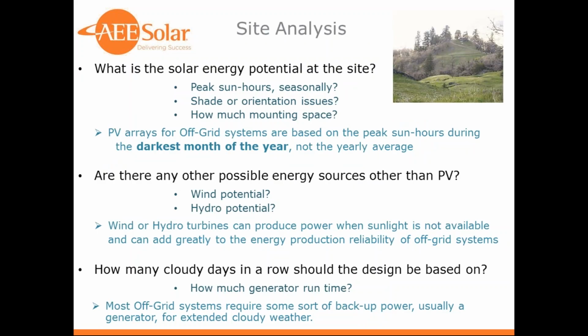So then we need to do a site analysis. What's the solar potential of the site? What's the peak sun hours? What are the seasonal effects? How much shade is the PV site going to get? Are there orientation issues? Are there a lot of trees or cover, that kind of thing? There might be mountains or other buildings that might shade a PV array space. We need to be aware of that.